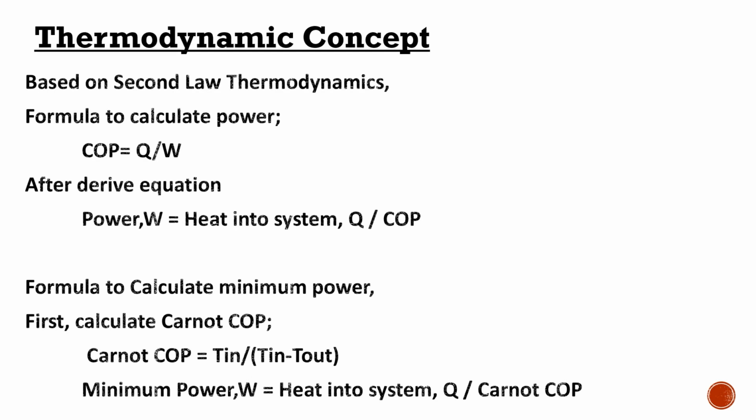So the question is related to a thermodynamic concept, which is based on the second law of thermodynamics. The formula to calculate power is COP equal to Q divided by W. So after derivation, to calculate the power, we divide the heat into the system Q by COP.